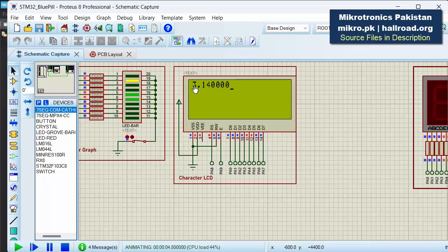So if you add the columns to it, you get the cursor to that particular memory position, and each line has 20 characters in memory. Even if your display is 16 by 2 and it has 16 characters to display, in memory it has 20 characters for every line. So the next line will be, after 20 characters, the third line.